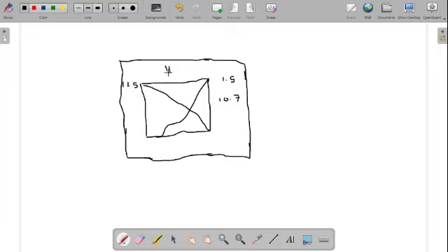If we add the 3 meters to this 11, that gives us 14. It means that this our profile line from this point is 14 meters. Meaning that between this point and this point here is 14 meters. So if that place is 14 meters, because this side of the profile is parallel to this side, that place automatically becomes 14 meters also.